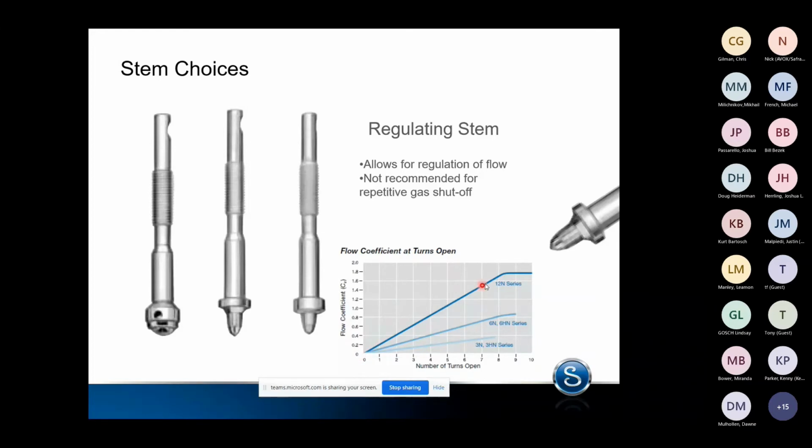Most of these are going to have a nice linear relationship. You're not going to see something that's going to do some weird S-bend or a different hiccup. And as we taper out all the way up here, the valve is wide open, and we're not effectively changing any other orifice through the valve.